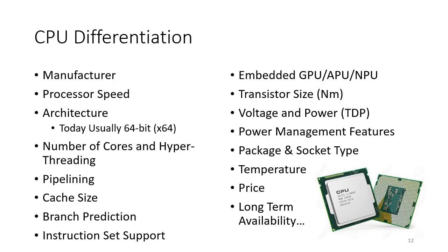If you need a low power device, then if you've got a high TDP, then you're just wasting resources. So often what you would do is you would look at the TDP and you might want to tailor that to your particular application. You don't want to have a too powerful computer because A, it costs more money, and also if it's using more power, you're wasting energy there as well. So power, TDP, is something that you will see, particularly with industrial PCs, because it's one of the ratings that you have some control over.